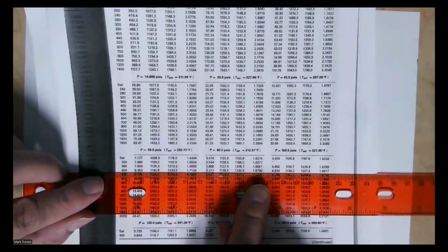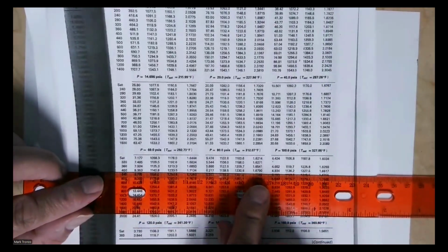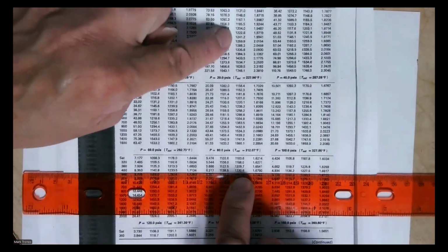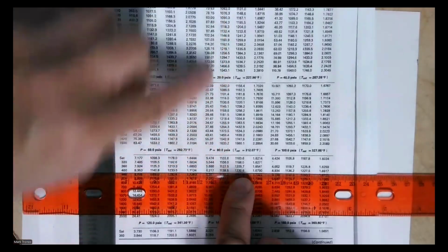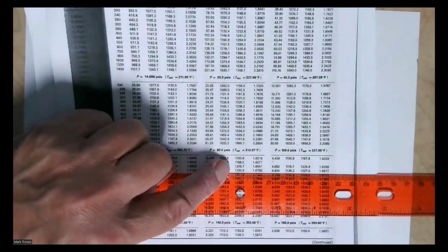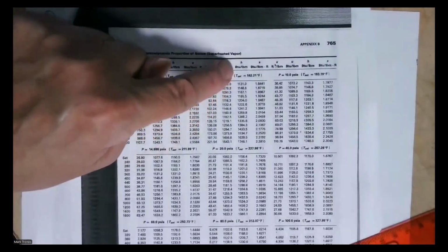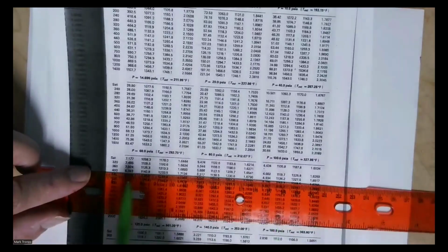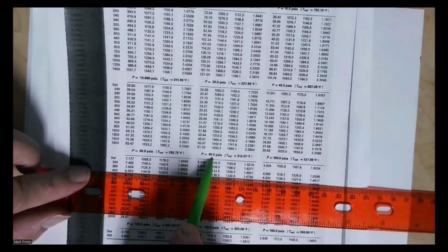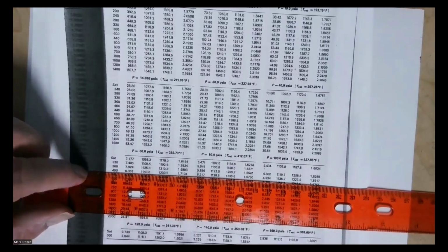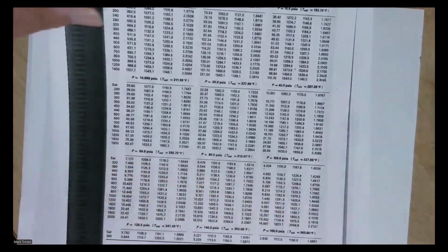And we look up 80 psi and 400 degrees. And of course, we're looking for the difference in enthalpy, so we have to find the enthalpy, and that's this column right here. This is giving us 1230.6. But let me just show you that up here, that column is enthalpy. So again, if we read 80 psi and 400 degrees, we get 1230.6.